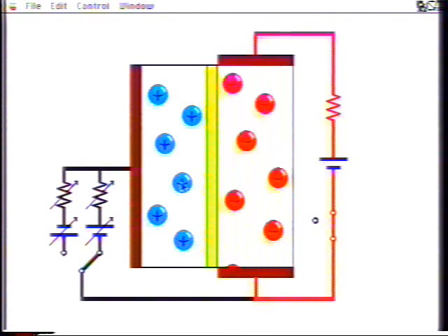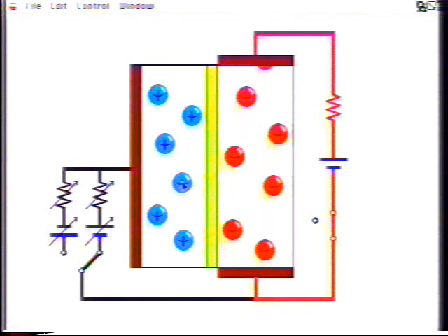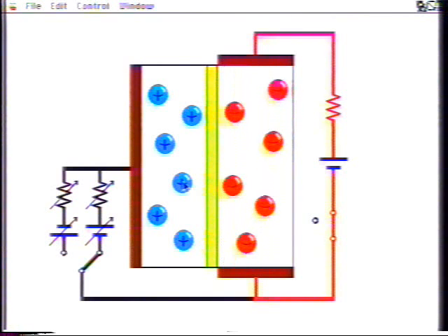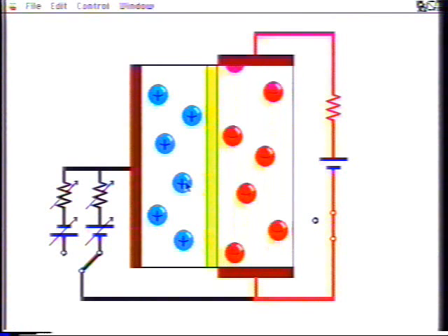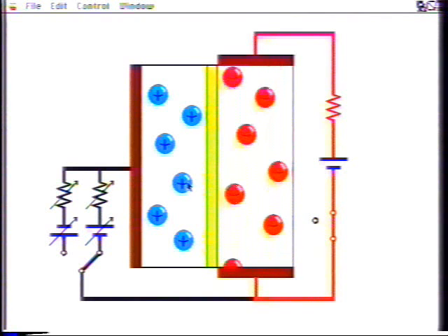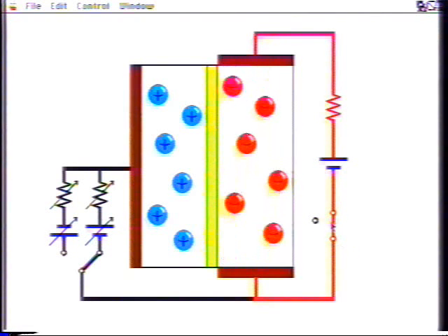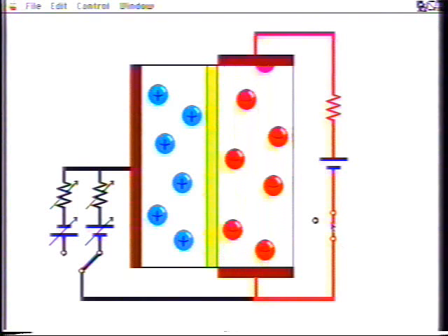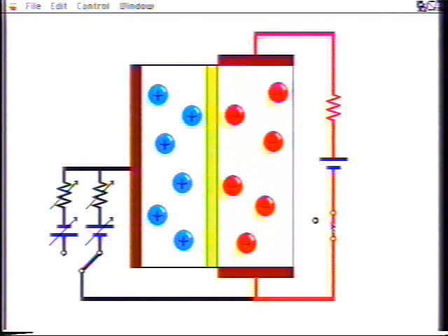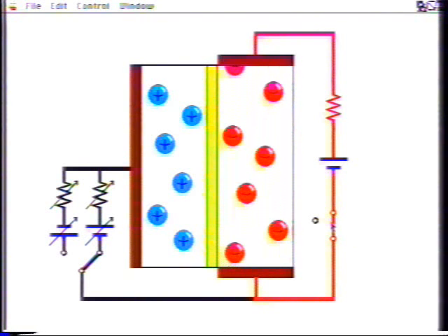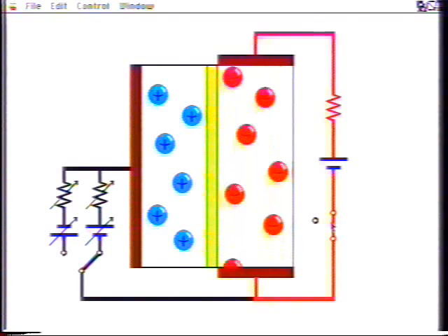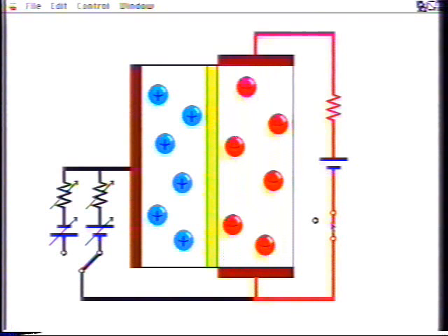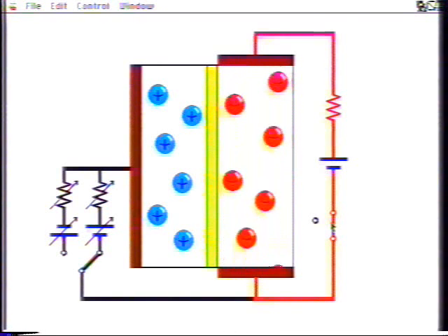Thus, the output current is controlled by the charge placed on the input electrode, and the property of a two-port active device is achieved. The FET acts as a controlled switch. When there was no positive charge on the gate, there were no available mobile electrons in the channel, and the source and drain terminals behaved as an open switch.